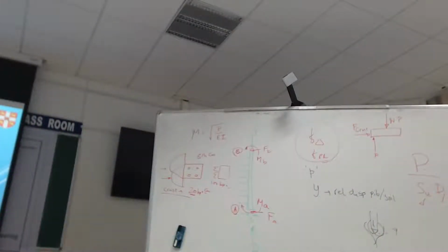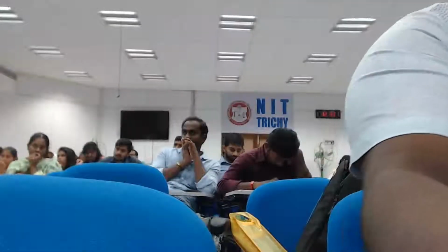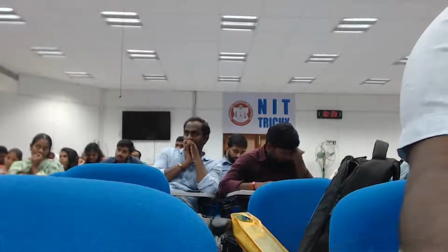You said you apply earthquake load with increasing amplitude. Once the soil liquefies, how do you take out the water for the next cycle? Oh, if you are doing a repeat set of earthquakes, it'll all come onto the surface. It'll stay there. Having a bit of water on the soil surface does not change your effective stresses, so it's not a problem.